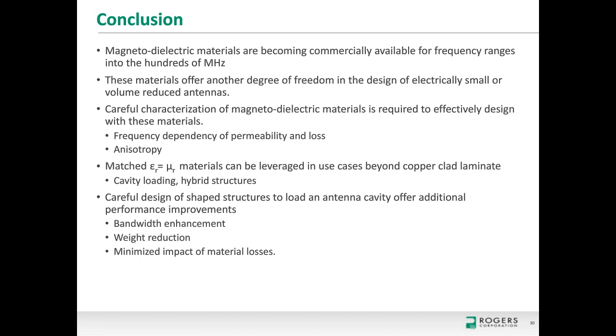And now because your dielectric constant is a result of a mix between polymer and ceramic, and the ceramic has a dielectric constant that's much higher than the polymer, you end up with a dielectric constant which is higher in plane as well. The z-axis, what we find is, for something like this mu equals 6, epsilon equals 6 material, where you have a permittivity of about 6.5 in the xy direction, permeability of about 6 in the xy direction, and permittivity in the z direction of about 5. So it's a lower permittivity in the z-axis than it is in the xy axis.